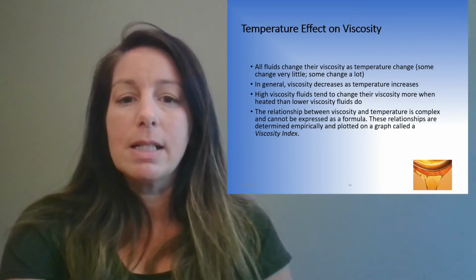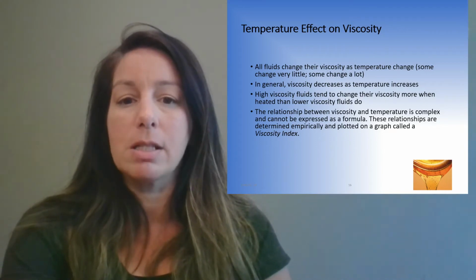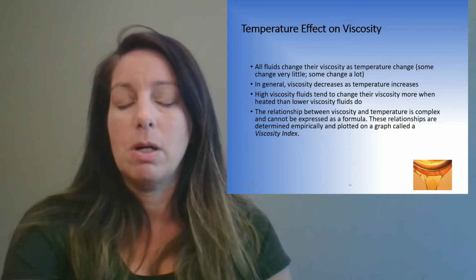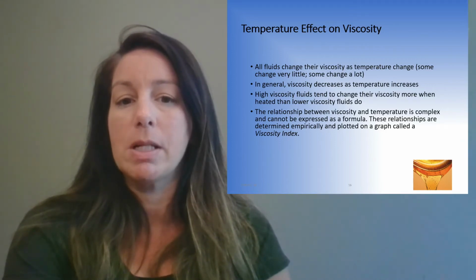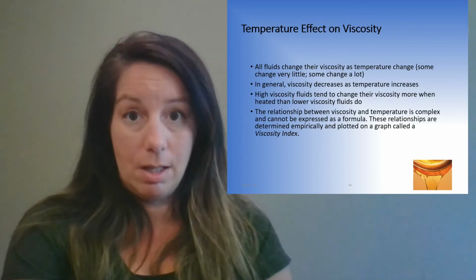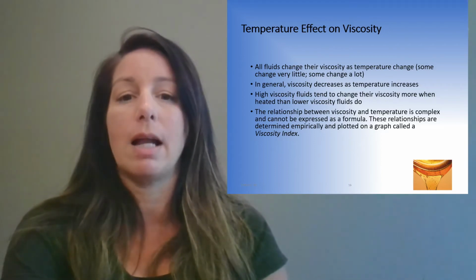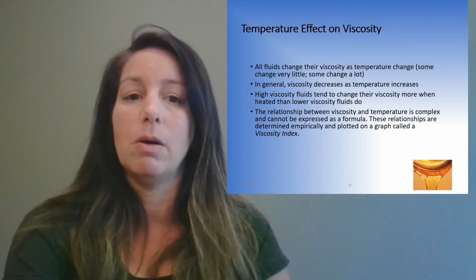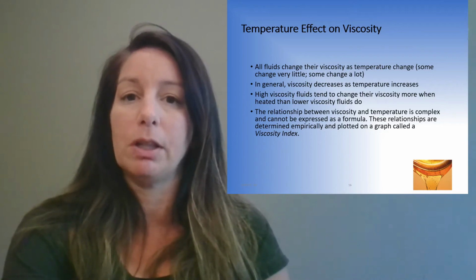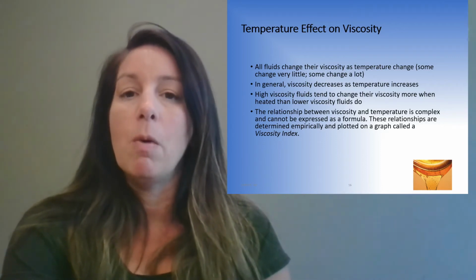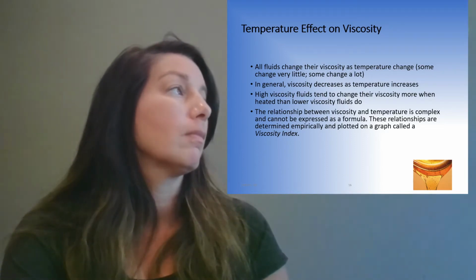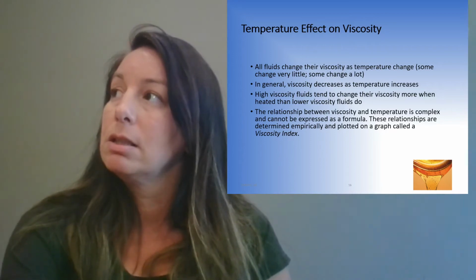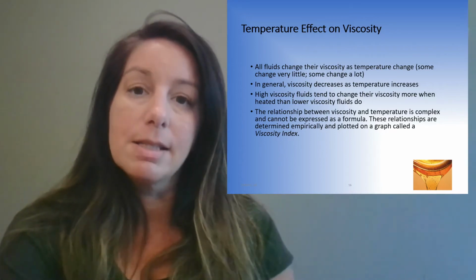So high viscosity fluids tend to change their viscosity more when heated than lower viscosity fluids do. So what were the high viscosity fluids that we talked about? Honey, molasses, those kinds of things. Lower viscosity, water. As you change the temperature of the water, it's not going to be more viscous at 50 degrees Celsius than it is at 10 degrees Celsius.